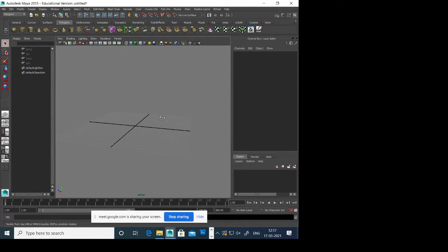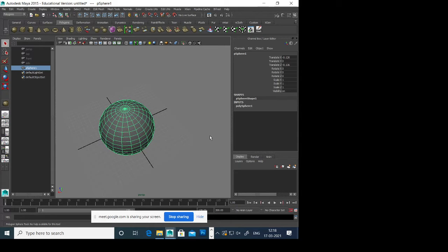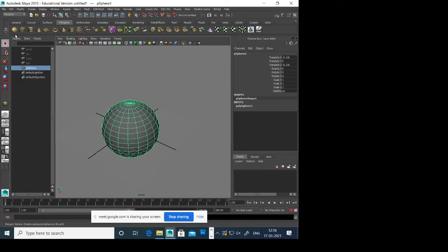No more mesh, right? Now you have all those options here: primitive shapes, sphere, box, cylinder, cone, basic primitive shapes. And by default, everything is unwrapped. That's standard to all the software. Click. So this is the older version. I'll ask him to update this so we can do it really easily. By default, you can see the moment I click it, my cursor changed, and now I can click and generate this. But in new Maya, you just click it, and it will generate automatically in the default setting.